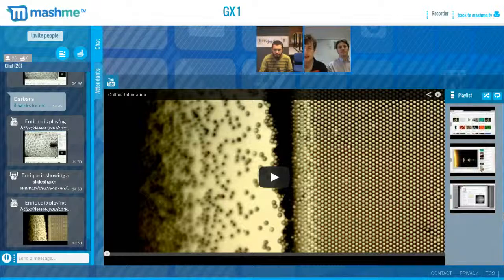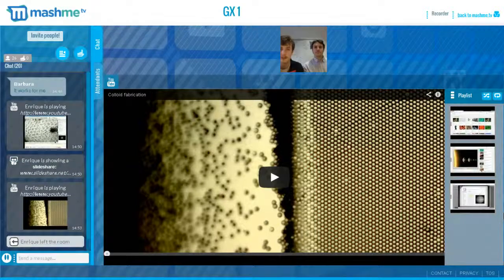So if you're playing, you should hopefully see the blade, the big dark bit on the left of the screen. As that moves away to the left, on the right you can see the polystyrene spheres are deposited from the solution. As the water dries, it leaves behind these polystyrene spheres on your substrate, but with a regular structure, that is the opal structure.